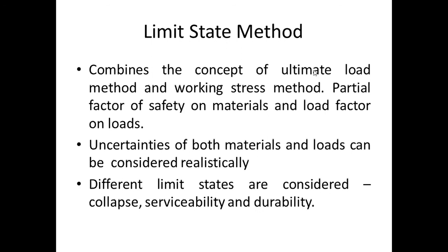The limit state method is nothing but the combination of the ultimate load method and the working stress method. That is, the partial factor of safety on materials and partial safety factors on the loads are used. So uncertainties of both materials and loads can be considered realistically. So it can be used as a realistic method, and different limit states are considered: collapse, serviceability, and durability.